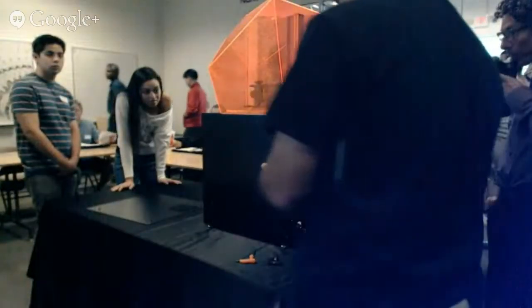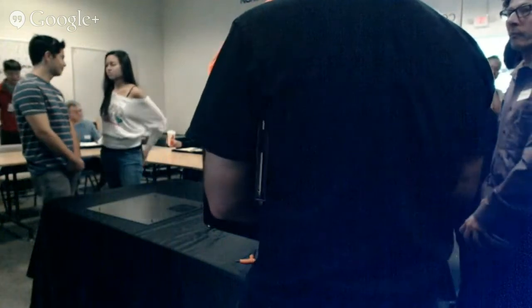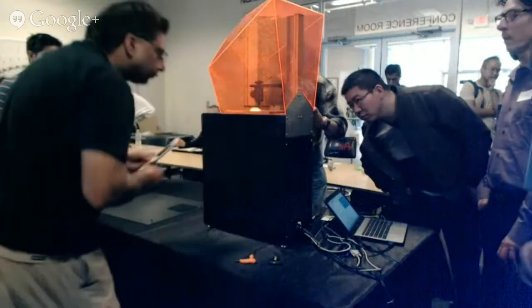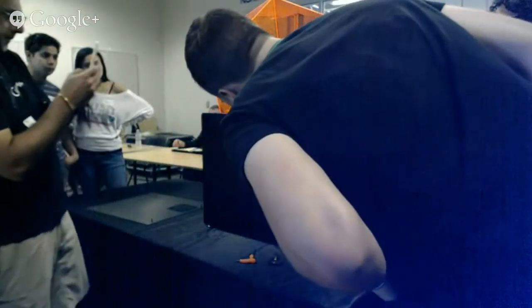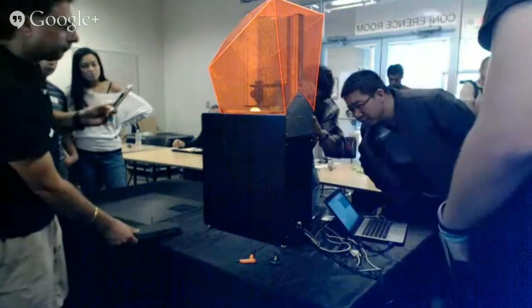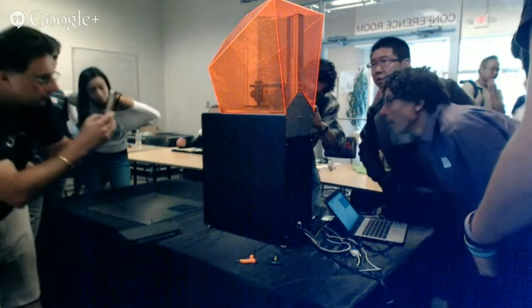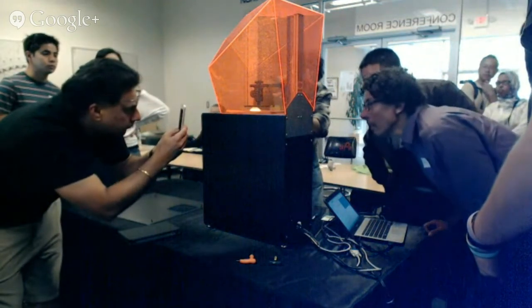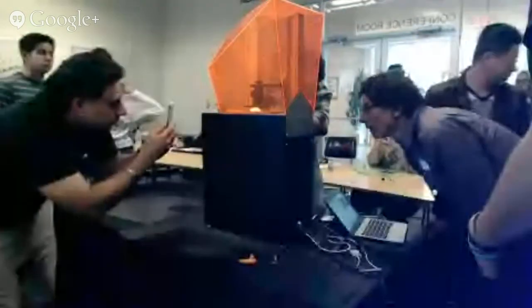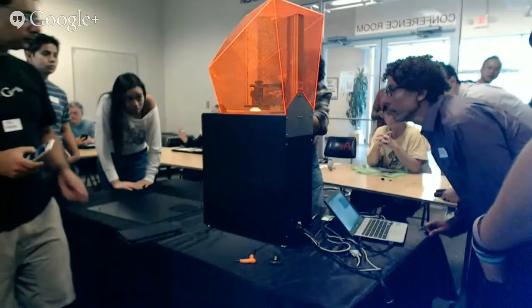This kind of metal is very low melting. Yes, if you need to get higher metals, then you have to get into lost wax. There is a type of resin that is designed for lost wax, for higher temperature metals. Yes, but then those are only one-time use. For the lost wax technique, you get a burnable resin. There's low ash resin that will burn out cleanly.